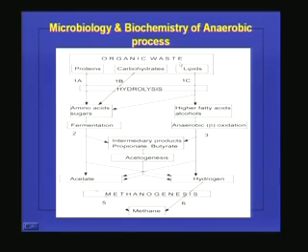The organic waste is coming, which contains proteins, carbohydrates and lipids. So hydrolysis is taking place. In hydrolysis, the splitting up of these molecules is taking place with the help of hydrolytic bacteria, and hydrolytic bacteria are few strict anaerobes and a few facultative type, and this facultative type bacteria are very, very important for the anaerobic process, because they will be taking care of the dissolved oxygen whatever is coming in the wastewater.